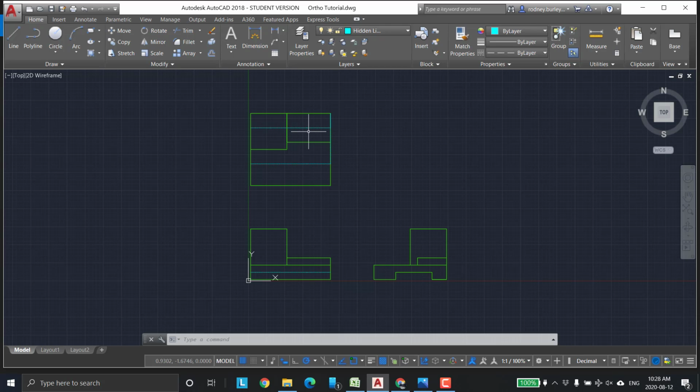And you also want to keep in mind, and we've gone over this before in class, by this point in time, that you want to simplify the drawing as much as possible. You don't need to put every single dimension in. In other words, if you have this dimension from here to here, and then this dimension from here to here, and then this dimension from here to here, you don't need to dimension this, because if the person needed to know that dimension, they could simply do the math. So you leave out certain dimensions by default and just make the assumption that the person is going to be doing a bit of math here and there.